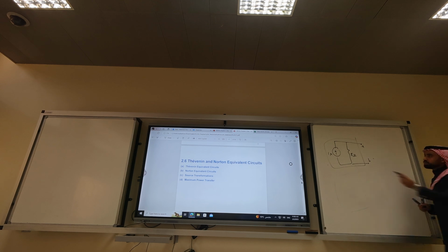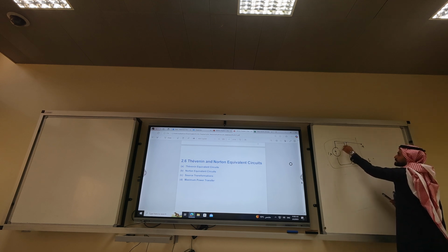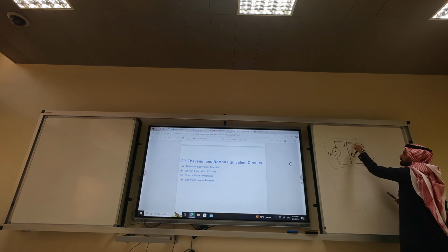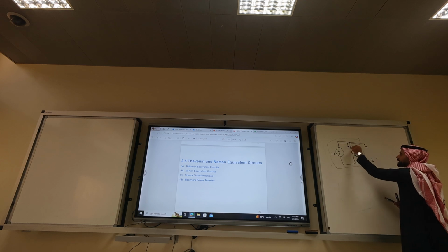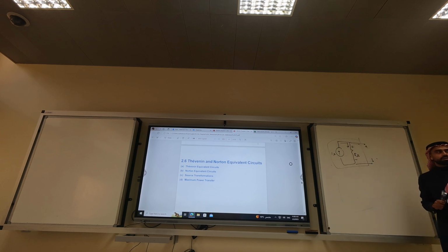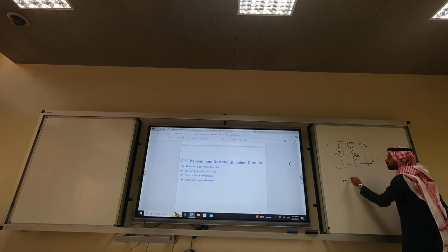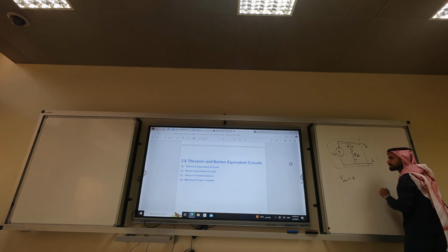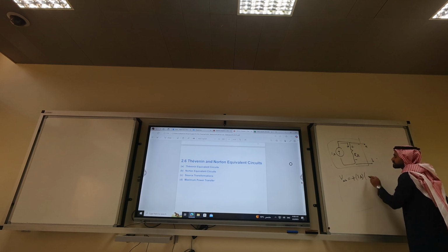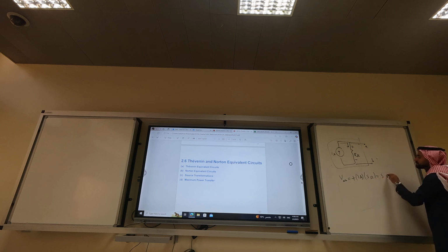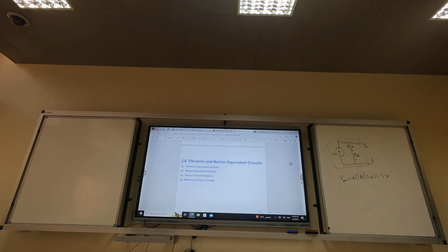Well, what should we do? This 1 amp will go here, right? Yes. Will it go there? No. Because it's a hanging cable in the air. With plus minus to avoid the passive sign configuration. Then VAB equals, what's the formula? Plus 1 amp times 5, which is 5 volts. So we can have the same voltage drop, right? Yes. Assuming this is an open.